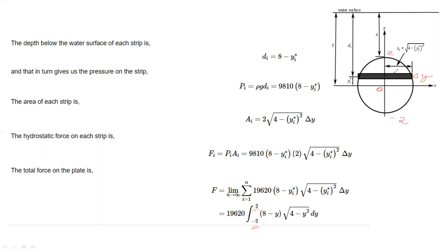In this case, this is a uniform area because it's that of a circle. So we set our center or origin of the x and y axes at the center of the same area. So this is now our integral, starting from -2 to 2. Now it's based on the dy, which will sum up all the strips that you will be making here for this particular circular plate. So if we will clear again our drawings and proceed,